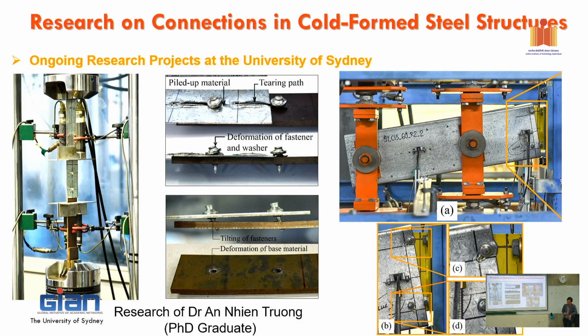Cold form is pretty tough to get to that one. But the combination of rotation and shear, we need to take into account. Even though in general, for structural analysis, when you run it, you assume that it's a hinge. But in practice, of course, you have two bolts, you get a bit of rotation, and a bit of resistance. So it's not 100% pin, but you need to design for that. But for structural analysis of the whole frame or the system, you assume that it's a pin end.